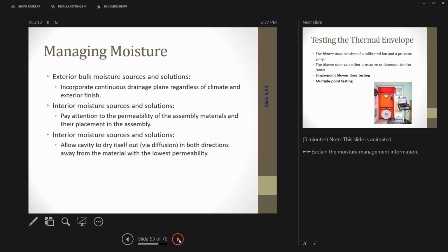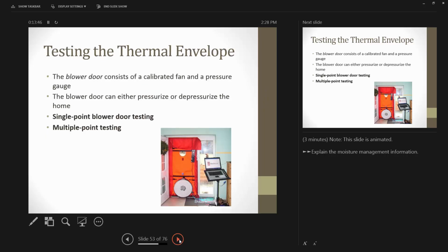So if we're using that vapor barrier in our climate and putting it on the inside wall to stop that moisture from getting in so it can't condense inside the wall cavity, if we use that same assembly in Georgia, what's going to happen? All that moisture is going to get in the wall and then it's going to condense on the inside. So there's an entire half a semester on heat transfer, moisture migration, and flow in 15 minutes, so I'm sure it all sunk in.